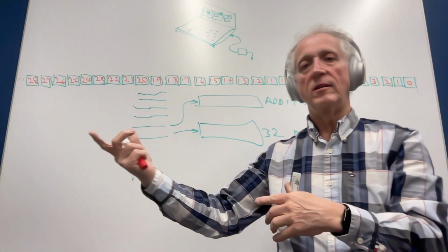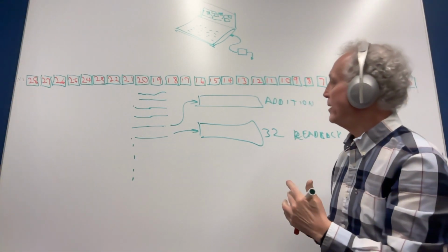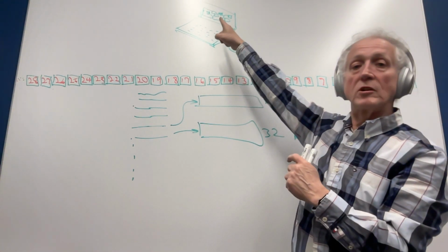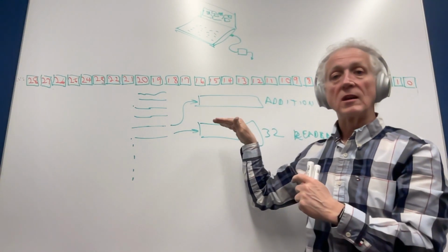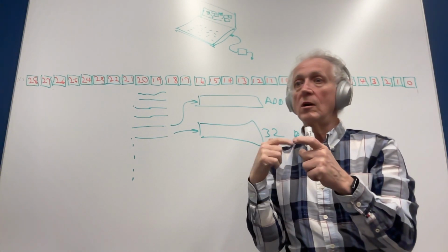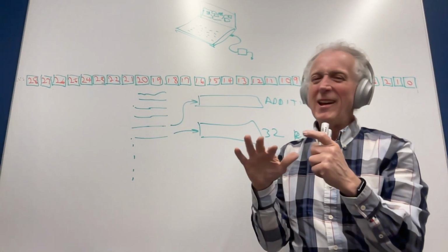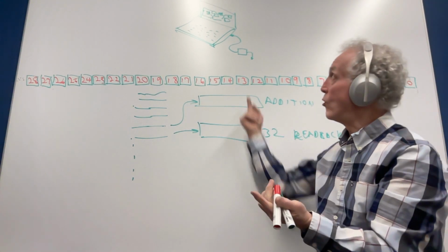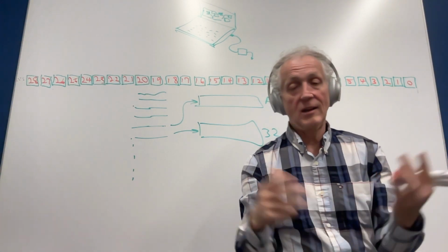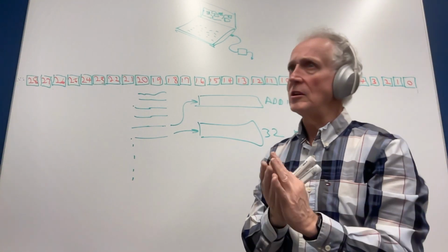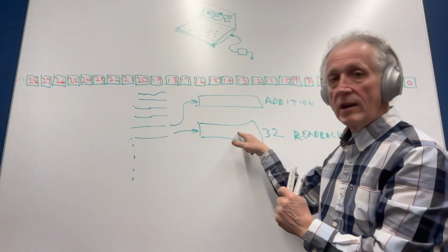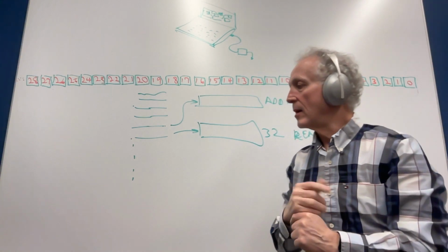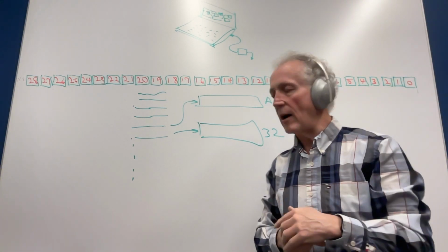I'll show that to you a little later in this video. But anyways, that's all it does. It grabs that memory location and puts it up on the screen at that particular instant. If you set the readback to continuous readback, it isn't quite continuous, because every sample period at 48 kilohertz would be 48,000 samples a second. No, it doesn't do that. I believe it's every 10 milliseconds. It'll read and show it to you, read and show it to you. So it can still miss a lot of values, but it gives you somewhat of a continuous readout.